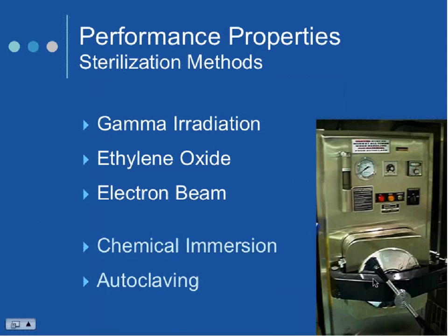Gamma radiation is a great way to sterilize parts, but it does typically have an effect on those more glass-like plastics because it's a longer dose or exposure. 6 to 12 hours is not unusual. And so it has a tendency to color change the materials. Makes them more yellow or brown, and that's why you see a lot of polycarbonate out there that's that purplish gray color, so that the shift isn't quite so yellow. We don't like yellow in the medical industry. It makes it look old. It also can embrittle the substrate. And again, because our adhesives cure into a plastic, you just need to think of them as a film of plastic, and they can work the same way as the plastics that I'm bonding to.